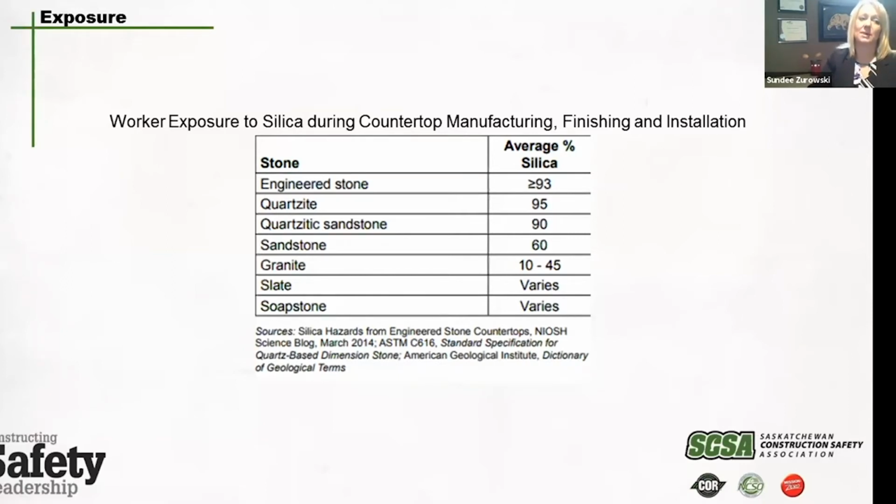Unfortunately, quartz countertops have over twice the amount of crystalline silica as granite and nearly 10 times the amount of silica found in marble. Workers in the natural stone cutting industry, as well as those involved in finishing and installation of both natural and manufactured stone, are at risk of significant silica exposure. In both industries, production operators such as sawyers, inspectors, including quality control technicians, and staff who perform maintenance and housekeeping duties in manufacturing facilities also may be exposed to hazardous levels of airborne silica dust.